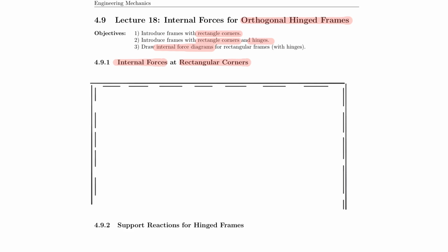However, this reference fiber that I just included defines where the positive and negative side of the frame is, as we will see in a second, or as we have seen before for our regular beams. And now, as always, I will release the internal forces at that location by cutting the frame. To do that, I'm going to eliminate some parts here, and I can do the same thing on the vertical components, just so that I can release my internal forces.